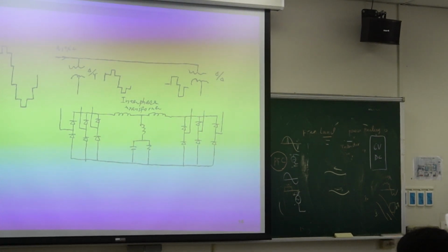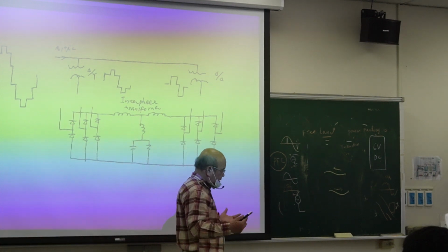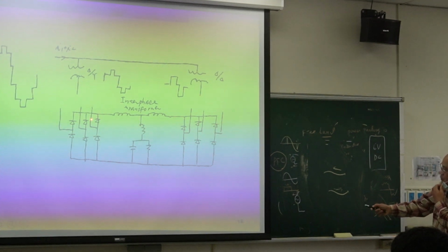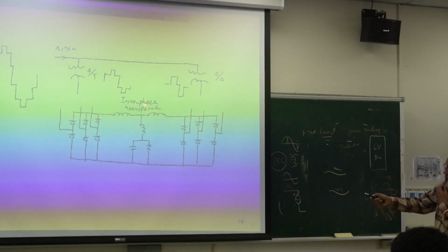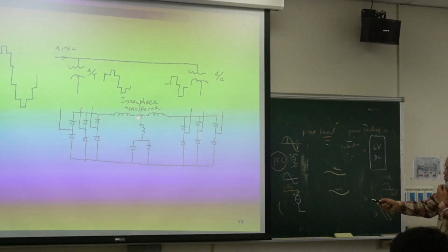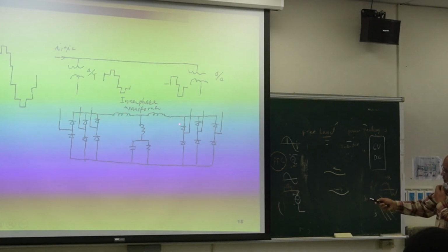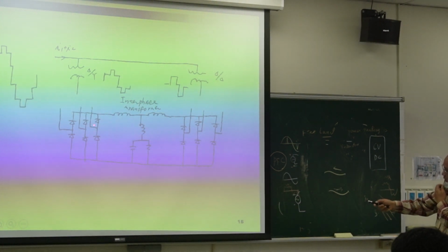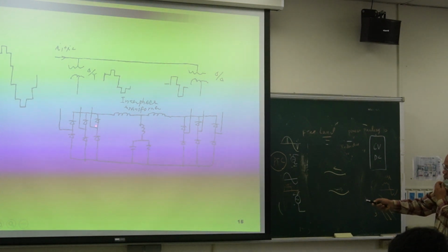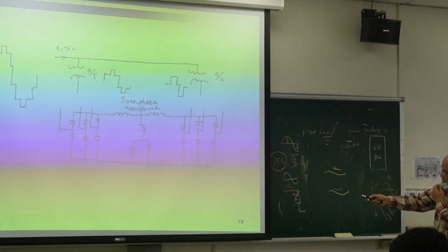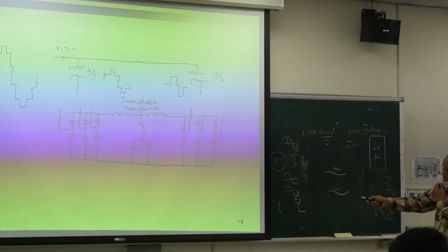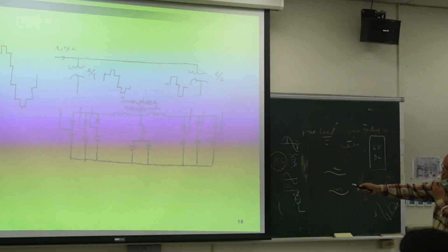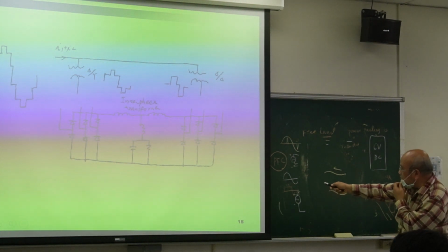The idea is like this. Because the load is random, it is not guaranteed. So now we put the loads together. So this is load 1, this is load 2. Then if you have 2 loads, then this voltage and this voltage cannot be totally the same. Sometimes they are different, especially when you use SCR. So they use an inductor to avoid the inner loop current becoming too huge. So they use an inductor to limit the circulating current.